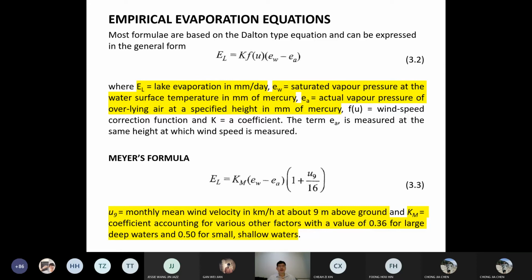For rainfall, we can use the rain gauge to know the amount of water we have. For the runoff, we can measure the river stream to understand how much runoff we have. And for evaporation from a reservoir, we use the evaporation pans to do the measurements and multiply by the pan's coefficient due to the scale effect. And we're still able to use the empirical equation.